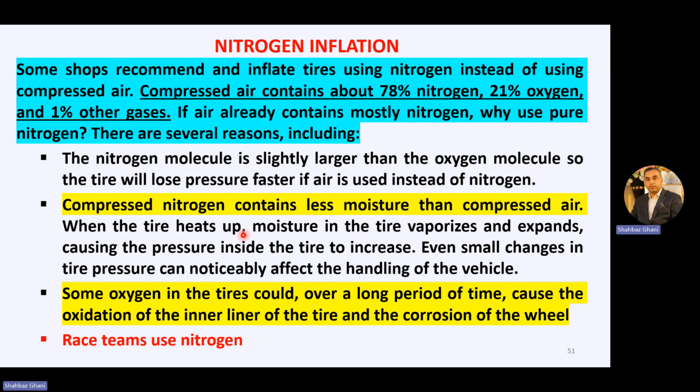When the tire heats up, moisture in the tire vaporizes and expands, causing the pressure inside the tire to increase. Even small changes in tire pressure can noticeably affect the handling of the vehicle. If your tire pressure is not correct, it will affect your steering, handling and your ride.